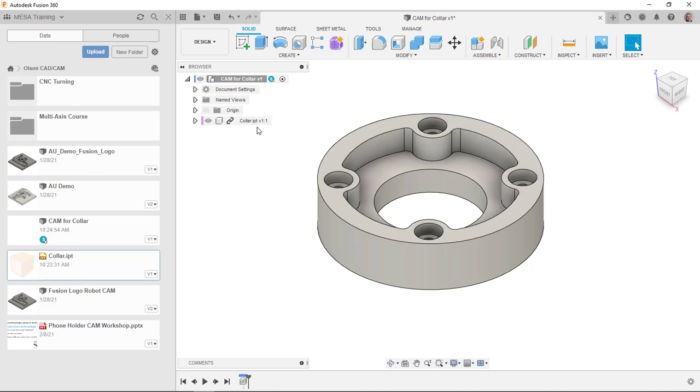So the next step here would be for us to create some toolpaths, go back to Inventor, update the file, make a slight change to it to see what happens, and then come over here and see the update so we can see that they are staying connected even though they're in two separate applications. Before I do that, though, I need to create some toolpaths on this one. So I'm going to stop the video here, take a few seconds, create my CAM setup, and I will catch up with you once I have that done.